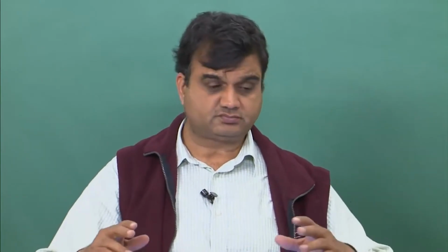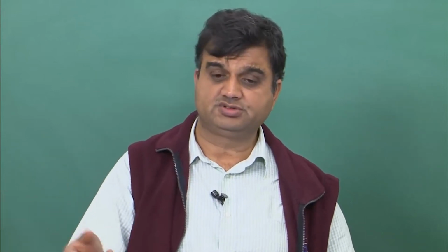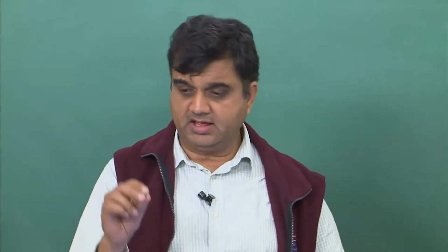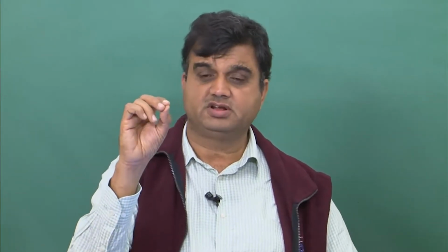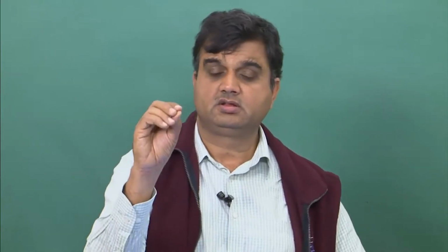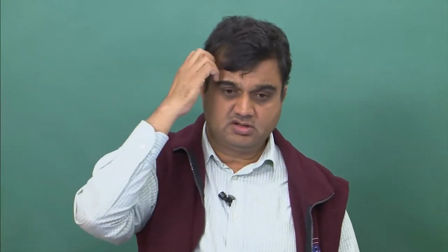So, if I have a 1000 hertz wave, its wavelength will be 340 meters per second divided by 1000, so it will be 34 centimeters. And if I have an object, let's say 5 millimeters in diameter in this noise field, then 5 millimeters is extremely small compared to 34 centimeters, which is the wavelength of the sound at 1 kilohertz.